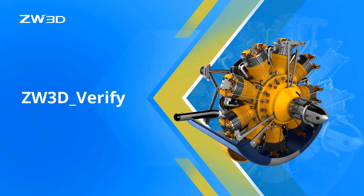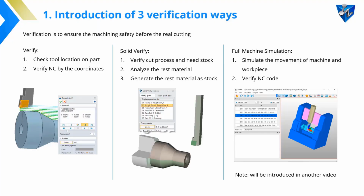In this video, we will learn about the basic verification ways in the ZW3D CAM module. As we all know, safety plays an important role in CNC machining. Before we put the NC code on a real machine, we need to check the toolpath and ensure safety. There are three ways to do the verification: verify, solid verify, and full machine simulation. Then what are the differences among them?